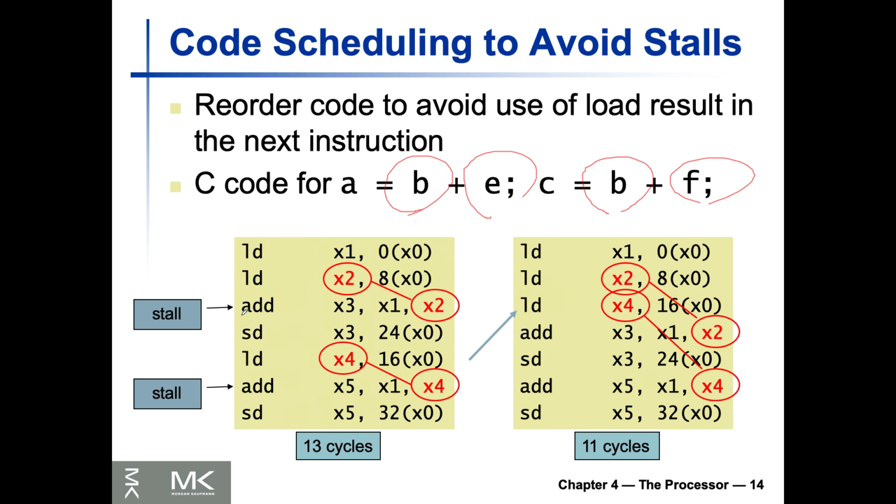So to avoid the need to access X2 right next to each other, the way we've been implementing it on the left side is we are loading the first one, loading the second one, which is the X2, and then right after that we add to generate this result for A. If you schedule it this way, you have to wait at least for one bubble or three without forwarding, just like that for the addition of these two to make this.